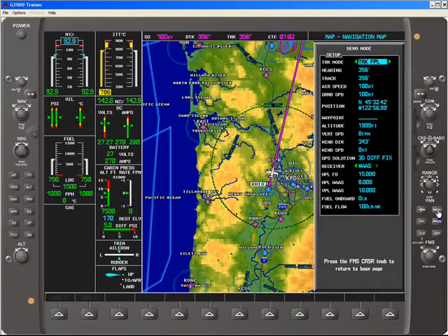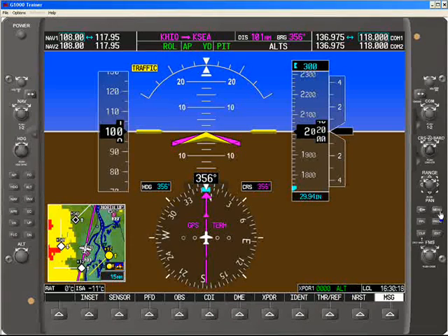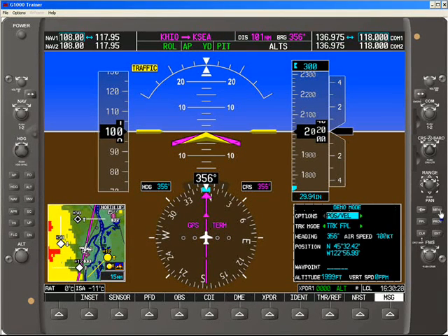This will display all the flight parameters that can be configured at any time during your operation of the PC trainer. Just as a reminder, demo mode is only available on the PC trainer. Actual aircraft software will not allow you to select the demo mode. The demo mode window also can be accessed from the PFD mode with limited selections of the flight parameters. To view the full setup, access the demo mode from the MFD mode.